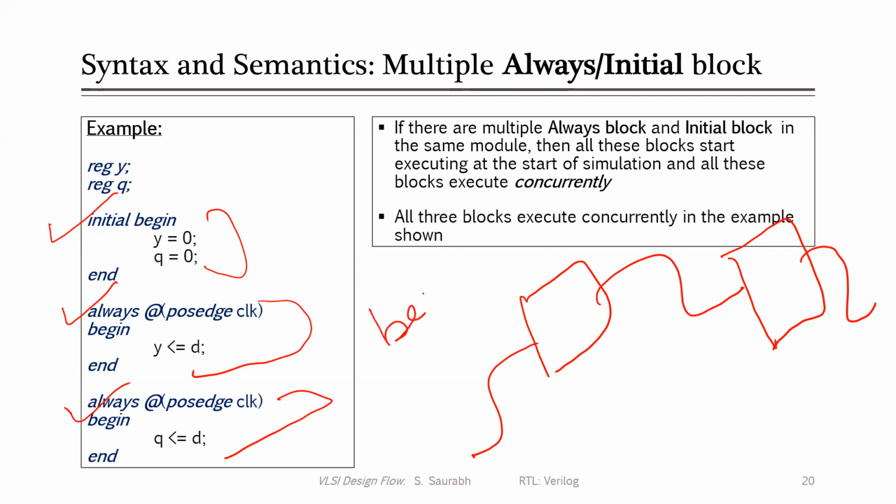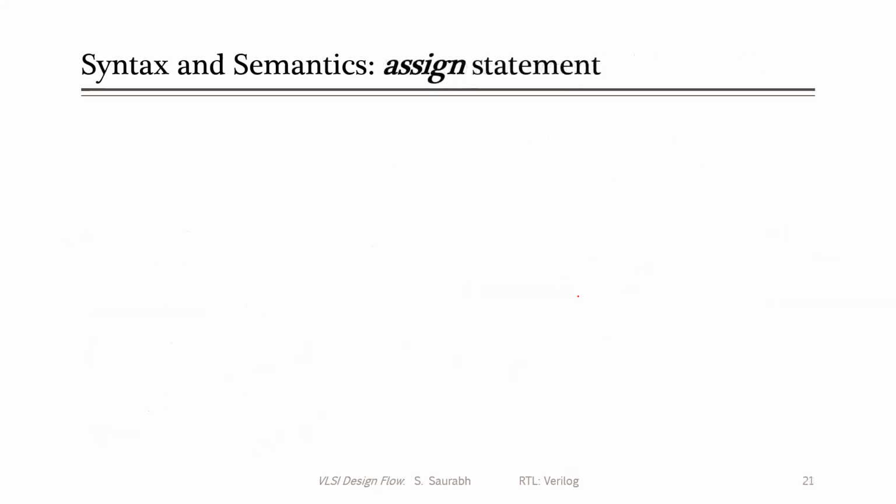Anything that you specify within begin and end is executed one by one, as in a general programming language. So you can use this feature to order a sequential circuit by putting the statements in a begin end block and ensuring that your circuit behaves correctly.